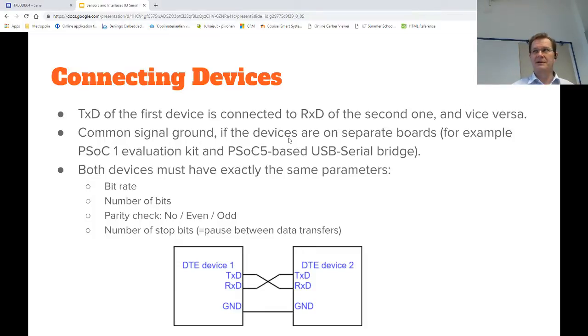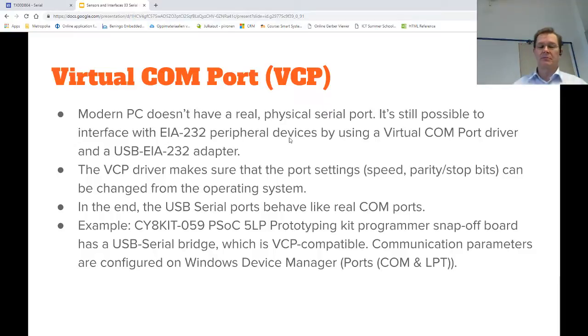You can, for example, think that okay, the other end is probably sending character 13 or 10 or both of those, carriage return and line feed, meaning you are hitting the enter, and then you change the baud rate until you start getting those characters. That used to be the method terminals used to talk with their mainframe computers back in the good old days, which were not good. They were just old. Okay, but this is the more modern kind of way.